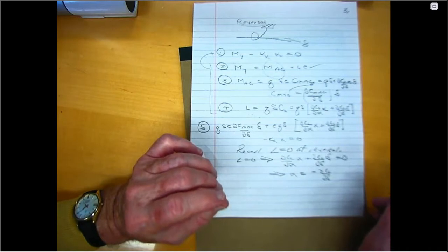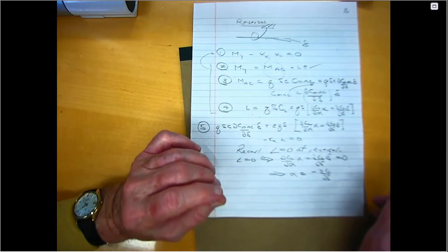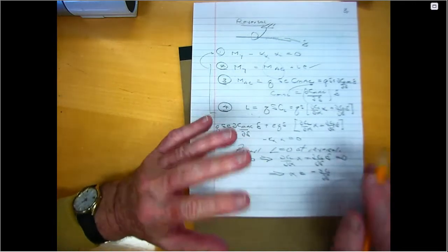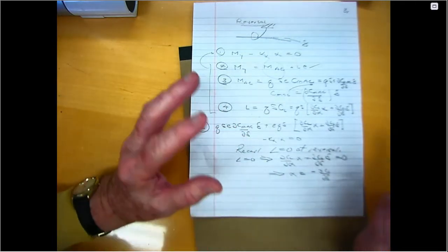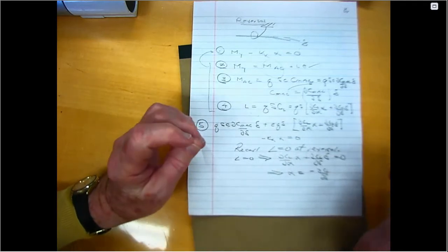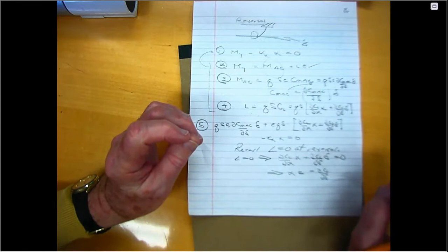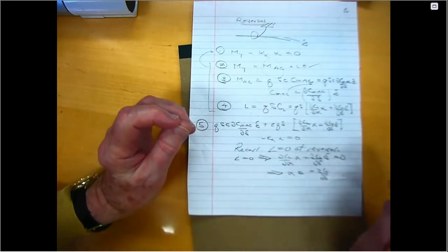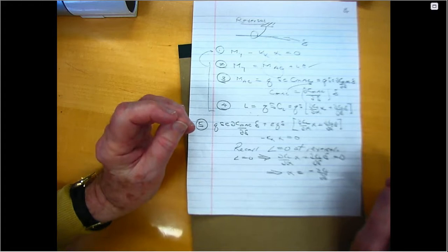Oh, why does it? Well, what we're doing is we're investigating under what conditions that can happen. And since you haven't done this analysis before, you may not realize that the lift could be 0. But what I'm saying is, I think there is a condition when the lift is 0, and we're about to find it. So we're saying, if the lift is 0, under what conditions will that happen? And it turns out there will be a critical value of dynamic pressure where the lift can be 0. Does that help? So we are assuming lift zero for the calculation.